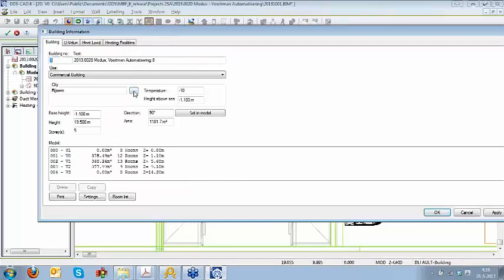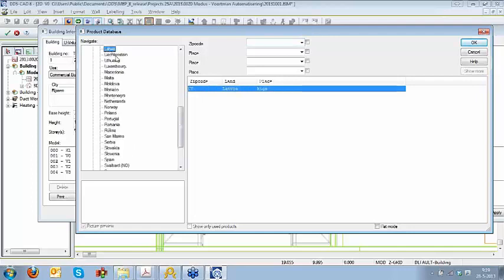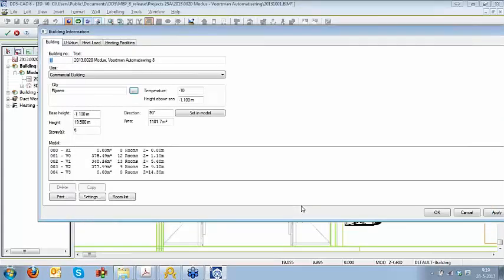So if we look at the location, in this case I used a location in the Netherlands, but as we can see we can have different locations, and from my experience and also from the experience of Carolus, like in Vilnius in Lithuania, we have a temperature setting within the database which is calculated as -16.7, and for doing heat load calculations this temperature needs to be, I think, -23.4 or something. So depending on the location also the heat load is calculated accordingly.